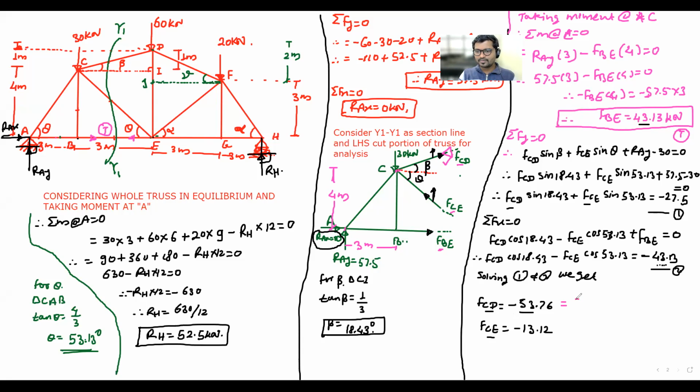So that is equal to plus 53.76 kilo newtons. I have made it plus, so first transfer its direction. CD's correct direction is downward here. At C it will be upward, so compression and tension, so transfer here T for tension. Okay, then for CE we have assumed up, that is wrong, so correct will be down.